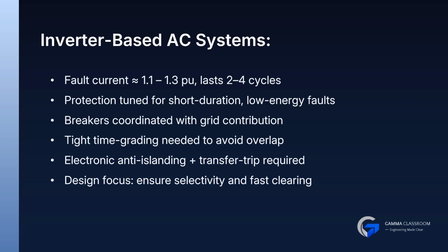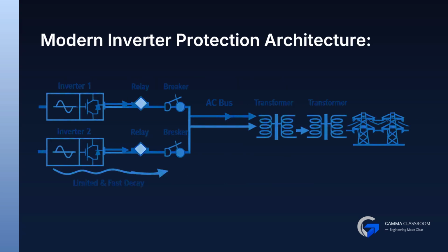This is the modern protection mindset for solar and storage projects. In inverter-based systems, protection must react fast and more precisely. Coordination depends on short duration, low energy faults, and tight time grading.